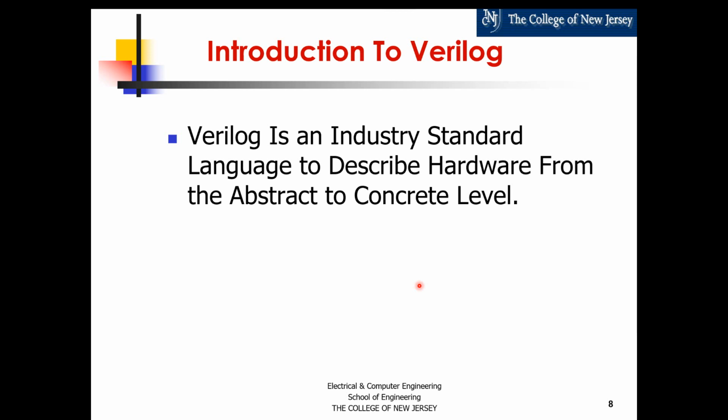And you can really describe hardware from a very abstract level to very concrete levels, and we'll go through the different levels of abstraction that you can use in Verilog, and I'll tell you the one that you need to use in this course, because here we're going to be actually developing hardware. So there is an optimum level of abstraction that you want to use, because if you describe at too low of a level, you're not taking advantage of the synthesis tool and you're not getting the productivity.